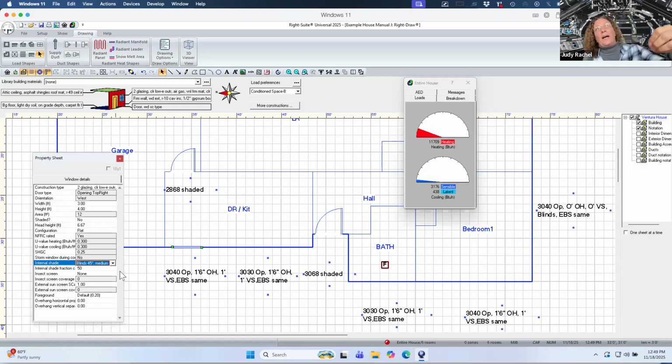And you also need to think about, even though when you're there, the shade or drape or whatever it is may be wide open, if you're not there on a design day, you need to either ask or think, so on a design day, this is a west-facing window at that hottest part of the day, are they going to choose to actually shade the window more than what you're seeing at the time? And so that's what you should be putting in right now for your load calculation, is how that shade would be during that hot day in July.